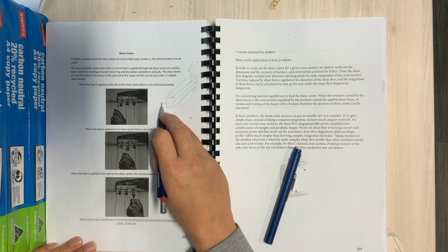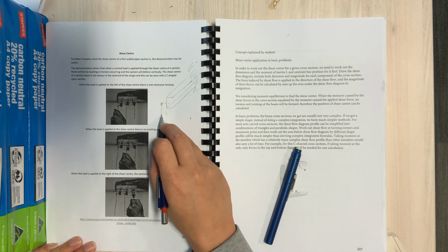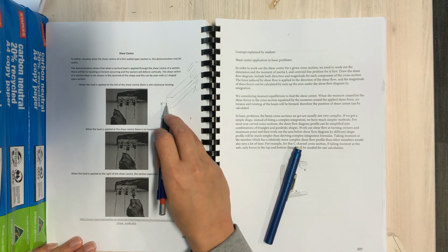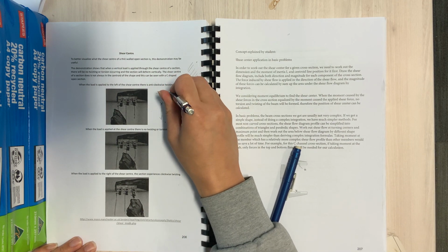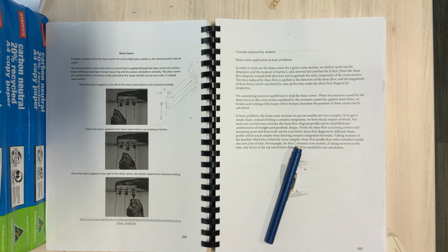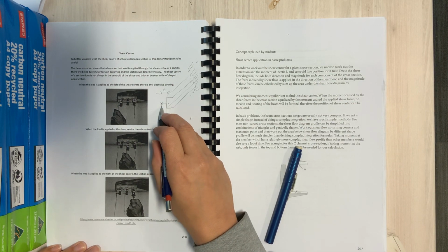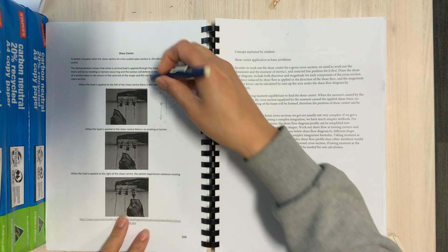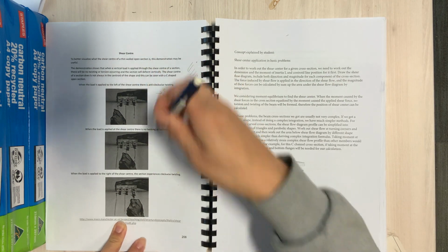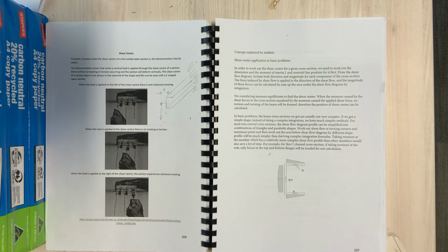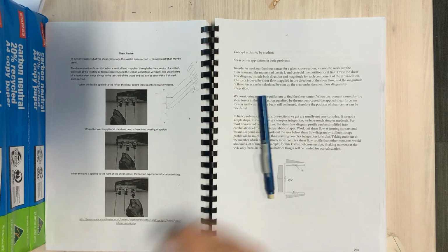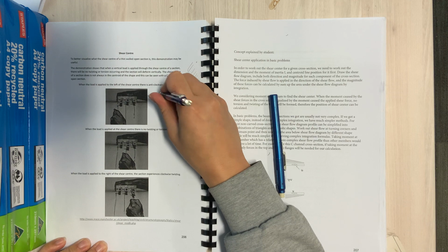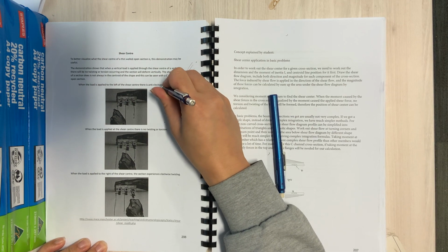So the general concept is, if your load or your shear force is applied eccentrically to the web at a position E, which we've got calculations to show how that E is calculated, if it's applied through that position, the section doesn't want to twist. Let's just leave that there since that shows the position of the shear center.